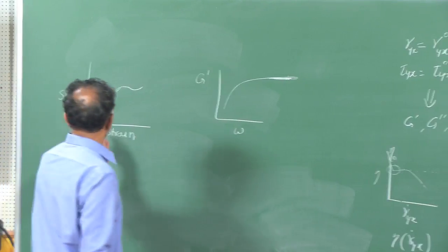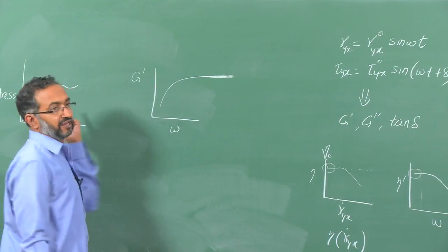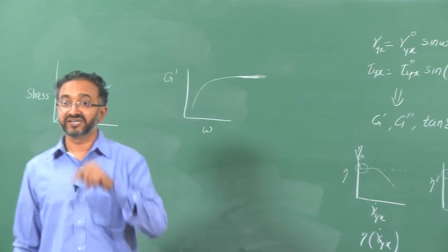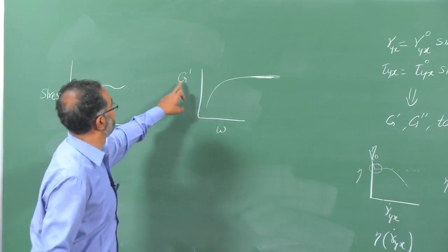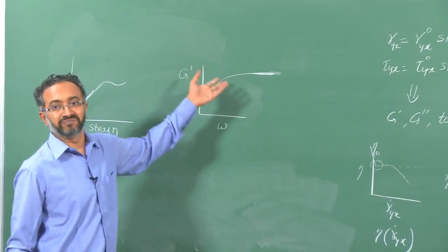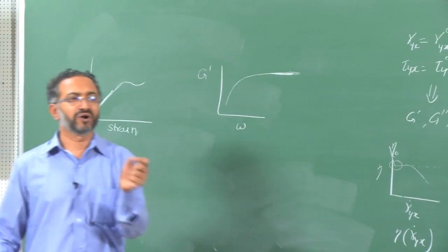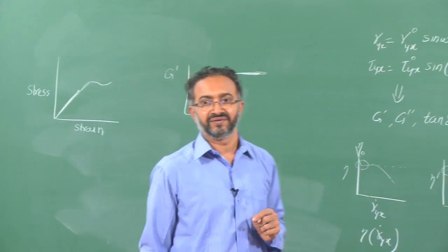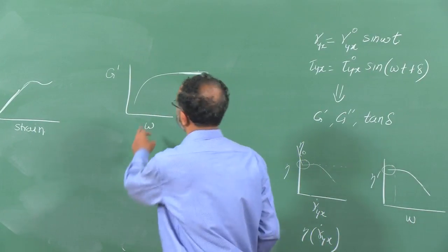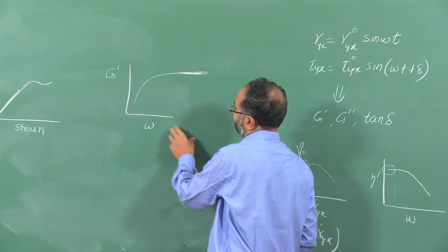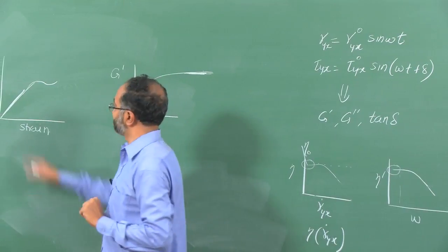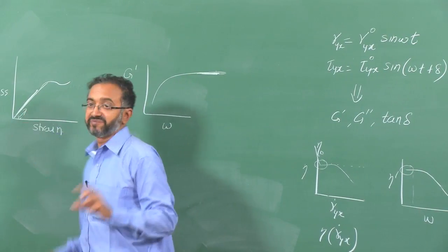Similarly, for the modulus that you measure, what we usually do is measure tensile modulus, from which we can calculate shear modulus, and this is usually shear the way we are defining it. Of course, we could also measure E prime, which is in tensile mode. So, those ought to be related to each other. But that is again at a limit, because we are also going to do this test with extremely high frequency and low deformation, and this also is low deformation behavior.